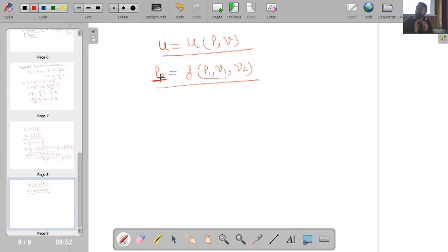It is also proven from this formulation that shock wave is ultimately leading to an increase in the pressure of the fluid, and obviously we have also seen an increase in density, so its specific volume is decreasing. So in a shock wave, if a fluid is moving through it, its pressure is increasing and its specific volume is decreasing. So it means a shock wave is nothing but acting as a compression process.